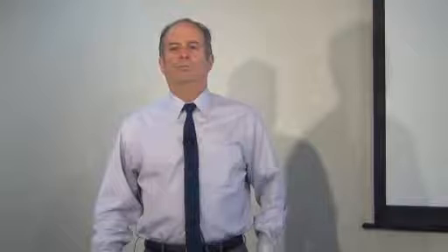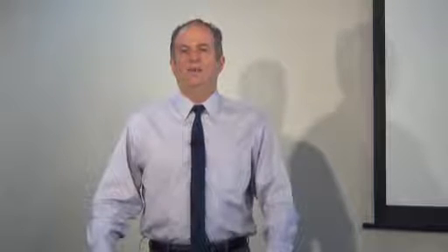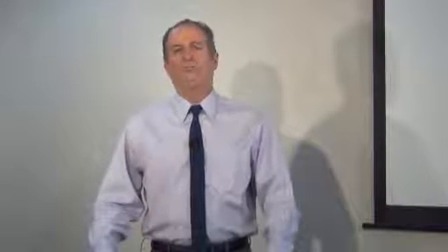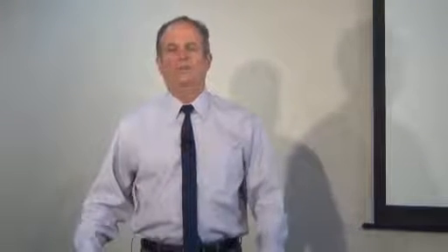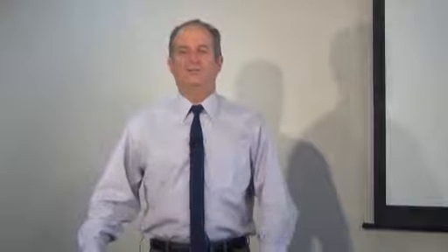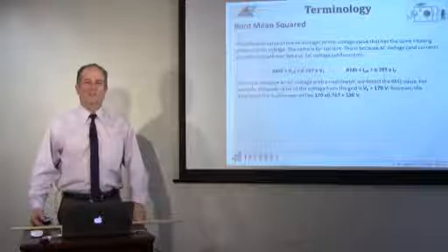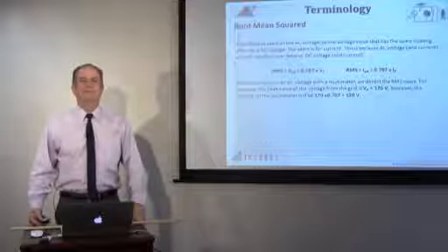Now, when we're looking at it backwards, we can say that when it comes to voltage, 170 volts peak, okay, has an equivalent of 120 volts RMS. So if you consider what voltage it takes to give you 120 volts, it's roughly 170. If you use all the digits, 0.707, okay?